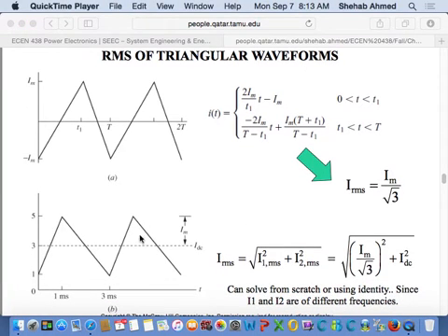So anyway, these DC power supplies will always have ripple, right? That was the objective of the discussion. We had this pulse waveform, we put a filter. This filter removed a good amount of the high frequency component, but it left some ripple. If I choose a filter with, for example, a lower cutoff frequency, I can remove more of the AC component, so what happens to my ripple?